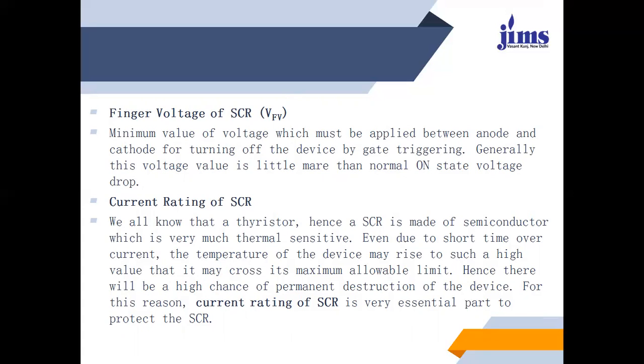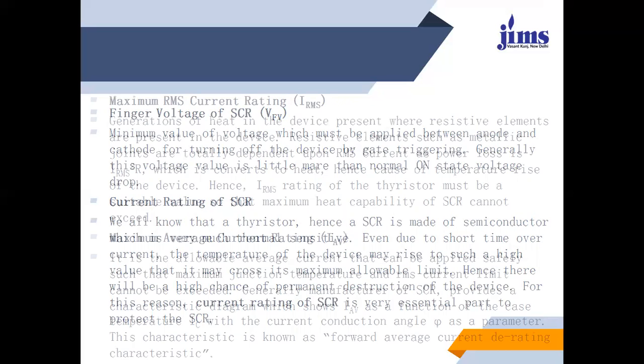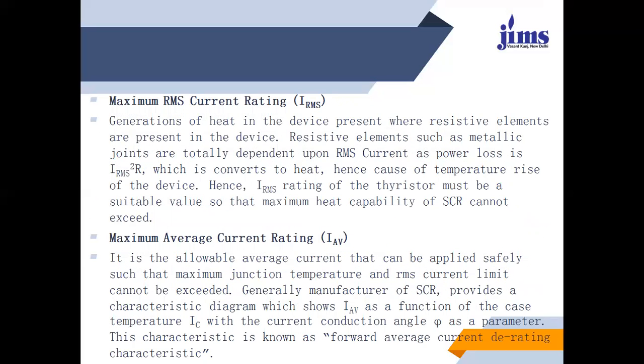Hence, there will be a high chance of permanent destruction of the device. For this reason, the current rating of the SCR is a very essential part to protect the SCR. Next is the maximum RMS current rating, IRMS.